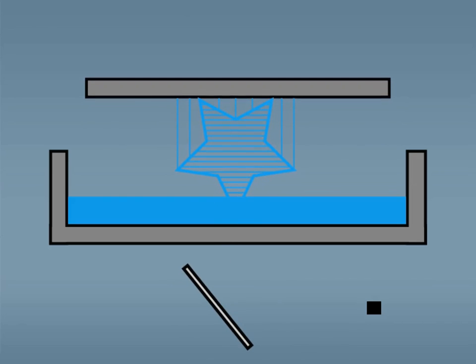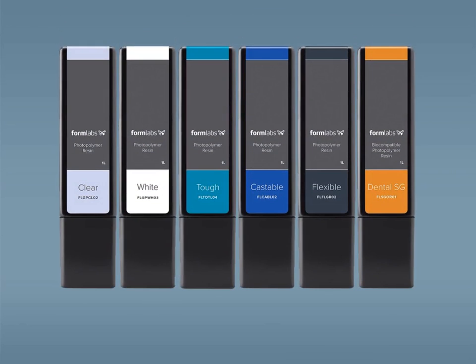the third axis to work on the next layer. Because the laser shines upward through the resin pool, the part is printed upside down and rises upward out of the resin. The resin used in the 3D printer is designed to have specific characteristics once the laser hardens the liquid into a solid. For instance, Formlabs offers a variety of resin types that produce different solid qualities.